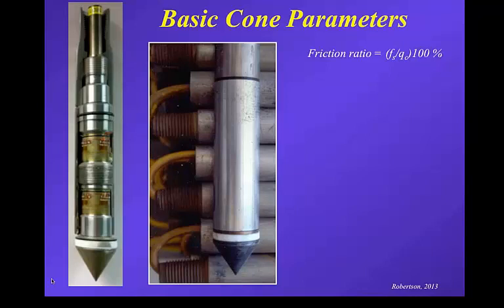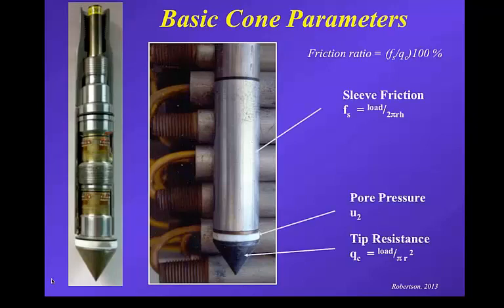Again, just a reminder about what the cone penetration test is. It's a probe you push in. Typically you measure at least the tip and sleeve friction, but increasingly pore pressure is added now, and it's the pore pressure that we're going to talk about today. It's often measured in the U2 location just behind the shoulder, although in the old days it used to be on the face of the cone, and you'll hear me mention that, often referred to as the U1 location. But quite often it's measured just behind the shoulder, the U2 position.